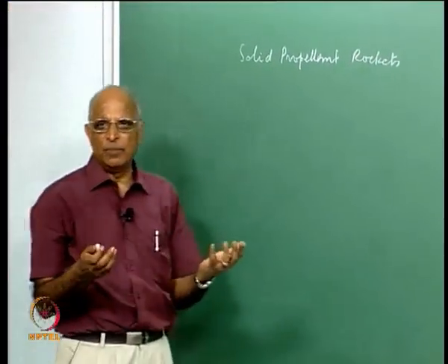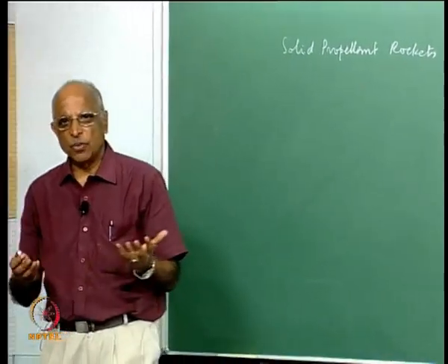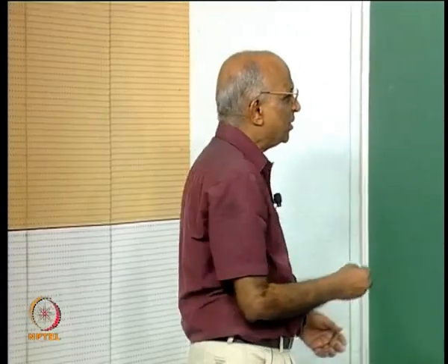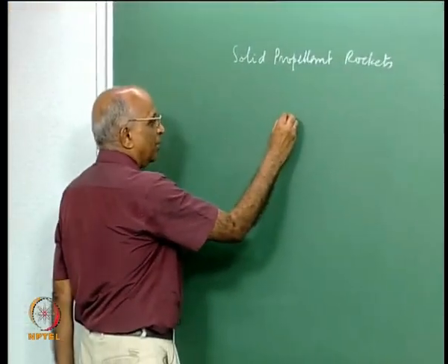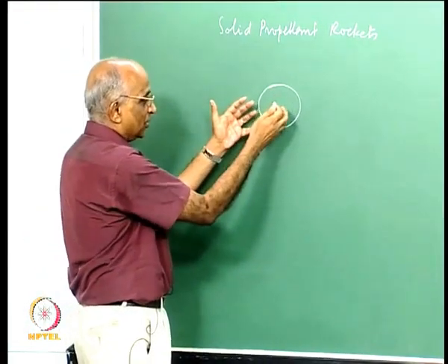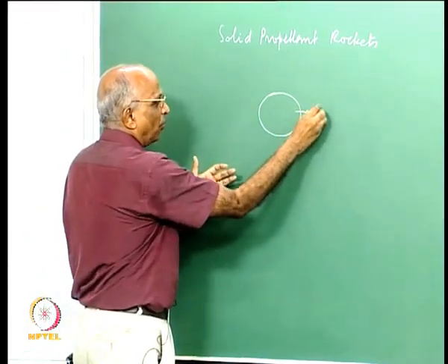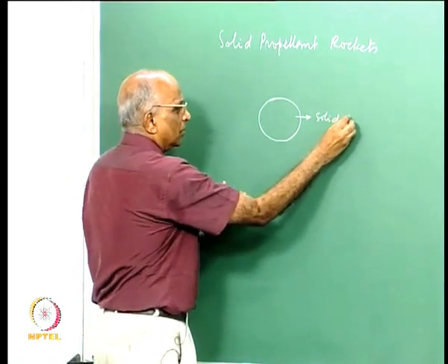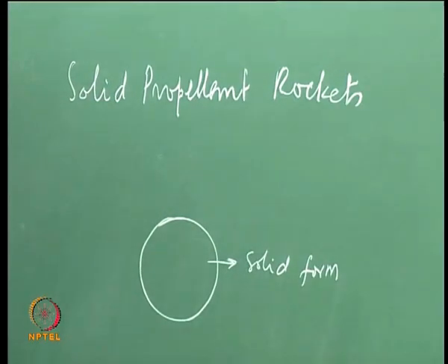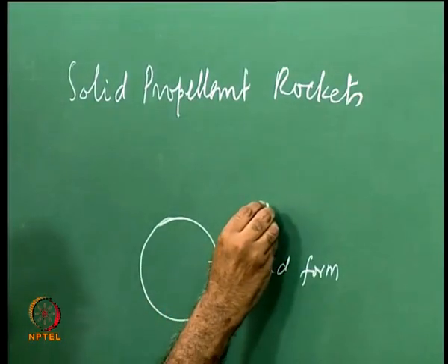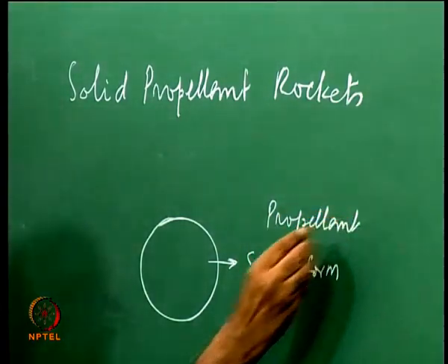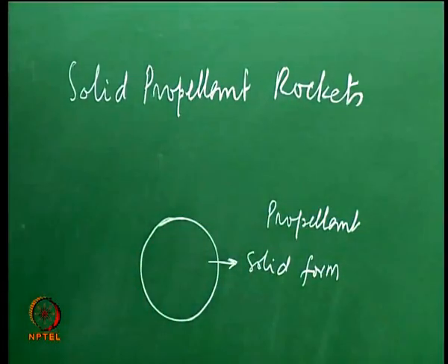consist of maybe double base, maybe composite modified double base, and also we said nitroamine propellants. Whenever these propellants are there, you have maybe some base in which you cure the substances, you make it into something like a solid form, and this solid is what constitutes, let us say, a solid propellant, and we would like to use it to generate thrust.